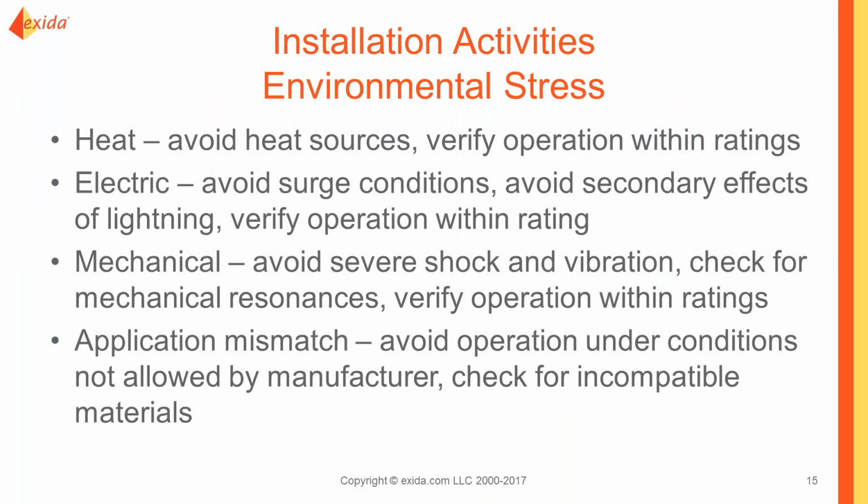We also want to be careful and be sure we verify the environmental stresses, so heat, electrical conditions such as surge or EMI, RFI radiation are important to consider. Mechanical considerations, shock and vibration, and also fit for use or making sure there's no application mismatch, such as checking for incompatible materials.